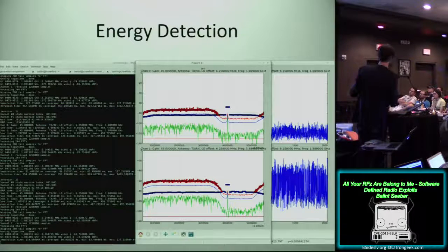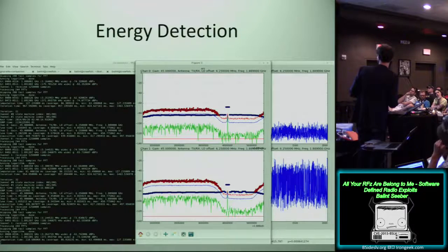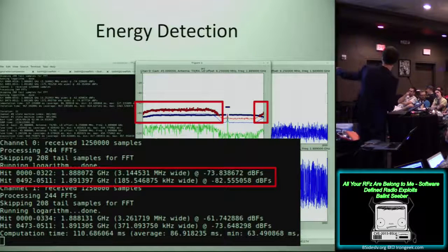And if you don't want to just capture absolutely everything, you can also do other tricky things like energy detection. So you might say, well, I want to capture the notion of my idle spectrum or a silent spectrum, and then any signal that pops up and exceeds some energy mask that I've defined here, in this case in blue, see how it's kind of flat, anything that exceeds that will be marked in red. Then you can see, hey, something's actually popped up, there's a signal there, I'm going to store that, and then I'm going to analyze it later. And then when it actually detected those signals, you can see that it found this hit there, and it stored that information, so you can process that for later.